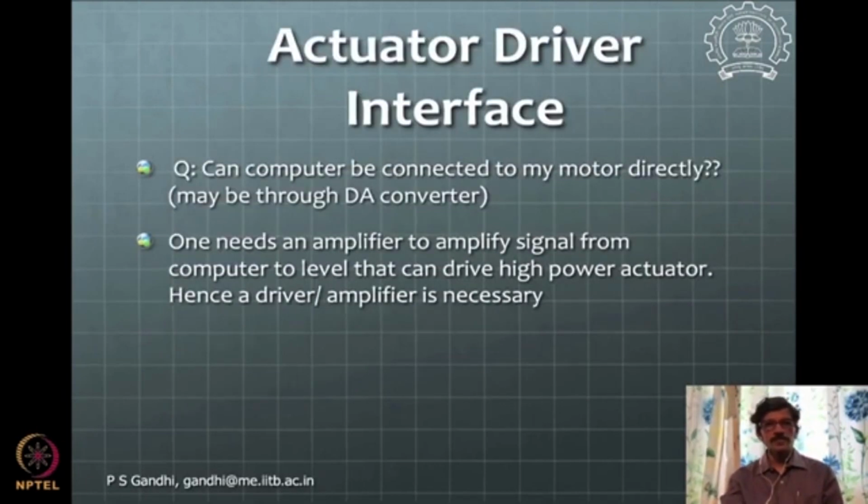Okay, so now let's look at why a motor needs a PWM interface. If you want to drive an actuator, you need a driver for amplification. You cannot say, I'll connect my motor directly to my microcontroller and it will start running. Imagine, you cannot connect a ceiling fan to your microcontroller and expect it to run, because typically these motors require larger power. Microcontrollers are supposed to be very low power devices.